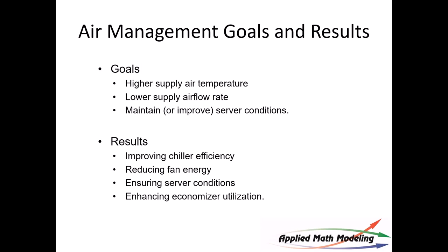A lot of economization is going on right now where you're basically taking outdoor air temperature and supplying it to the servers. And we see this in chiller design or cooling design. Sometimes they use evaporative media to do this. Sometimes they're just using dry air heat exchangers. Magnus, I don't see so much what we used to call free air, where they bring the air directly into the data center. I see dry.